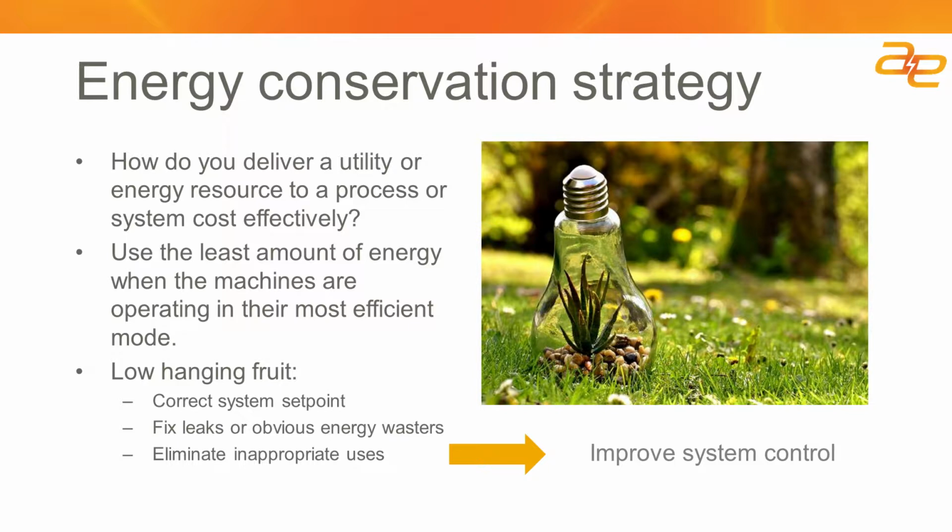Perhaps you've gone through and done an audit and fixed whatever leaks might exist, or other obvious energy wasters. Perhaps you need to make sure all of your pipes are insulated in terms of distributing steam or chilled water. Steam traps is another common energy waster within a facility.